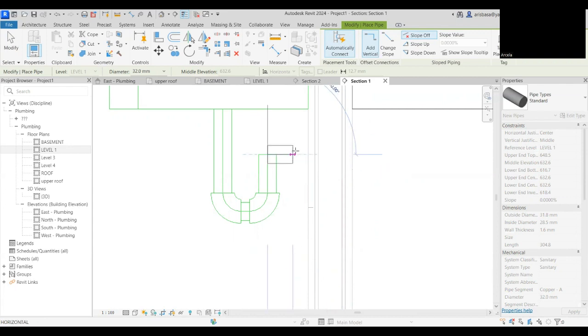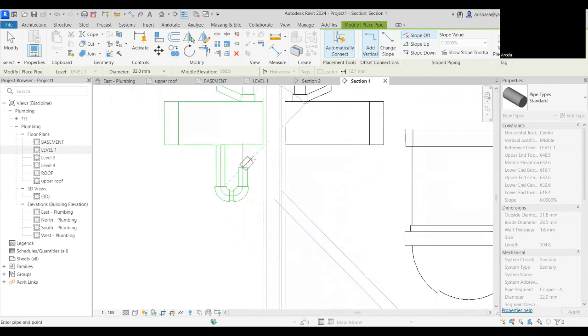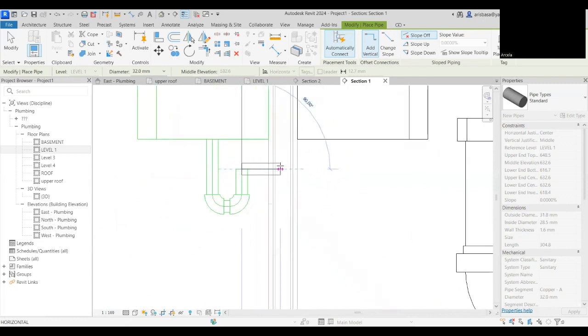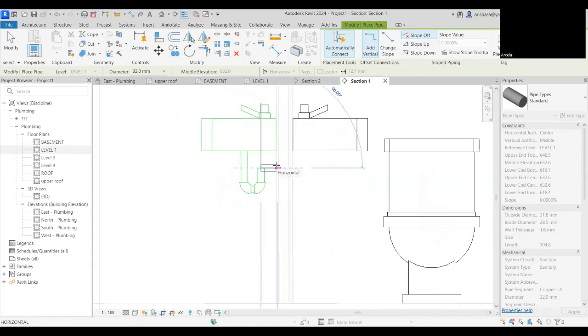Okay. So here in Qatar, the hand wash goes to the floor drain. Did you notice that? The floor drain. But my problem right now is I did not bring the floor drain that has the connector for these other drains. So the floor drain is just a normal drain. So what we'll do is we'll let this go out on the main drain. Okay. I'll just get this to go maybe here. Okay. And go down like that.